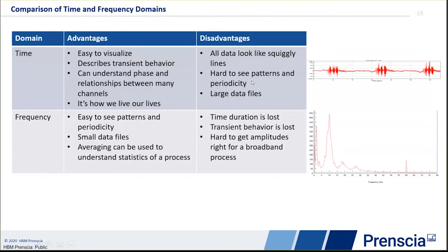The major disadvantage in the time domain is the large data file, which occupies more space on the hard drive. And in the frequency domain, there are certain disadvantages, like the time duration is lost. So you may not understand how much time it takes to capture the signal.